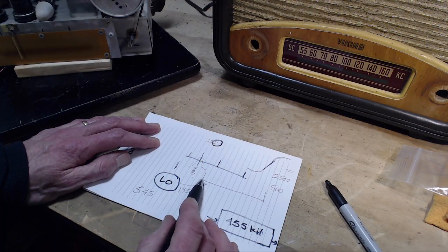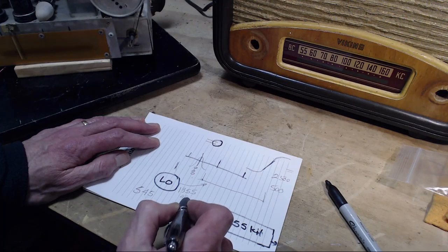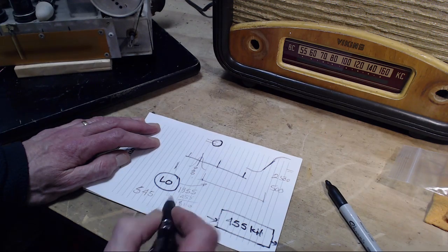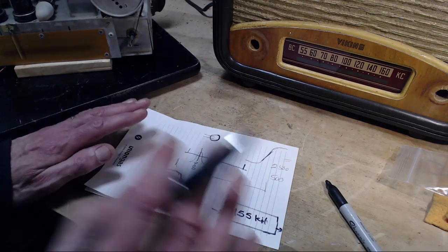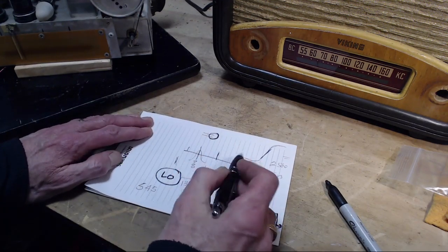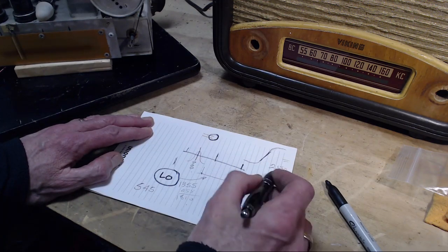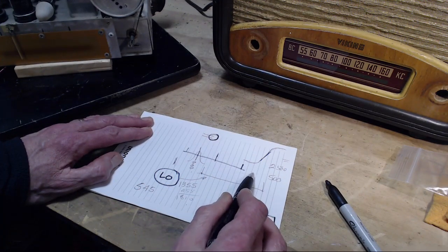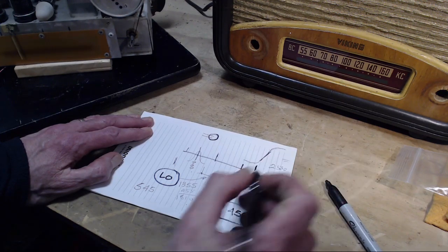Let's just see, what would that really be? So 455 on top of this would be, I gotta do this. 1810. Now, if there's a signal at 1810, my scale here is way off. But 1810 would be, well, the AM dial ends at 1600. So 1810 would actually be up here beyond the AM, beyond the range of the radio.